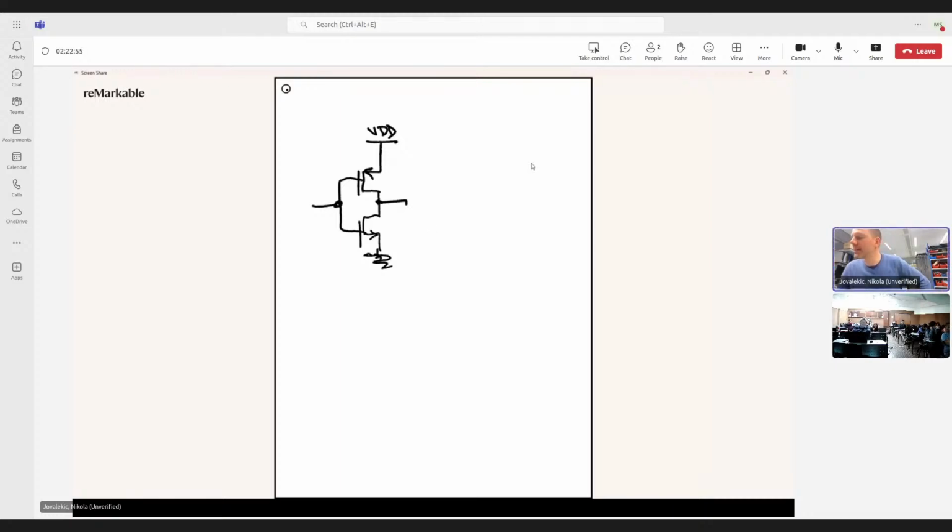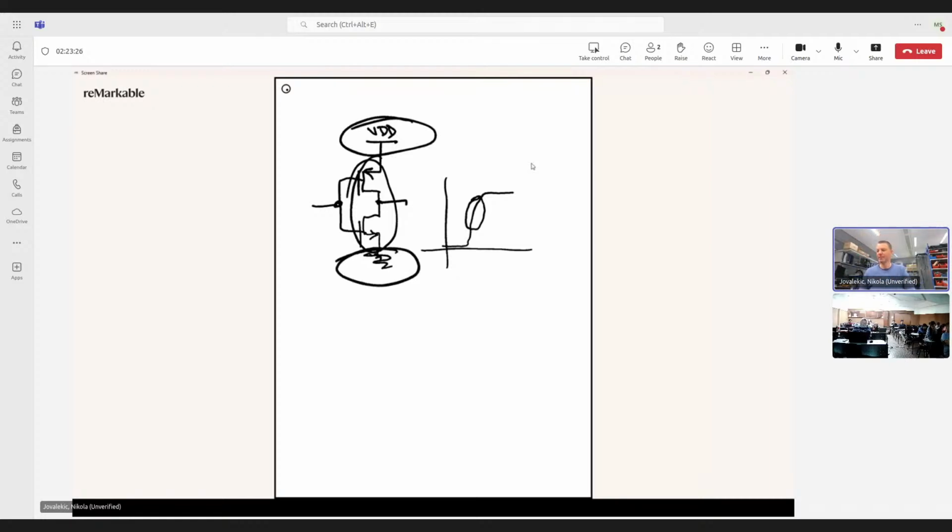So this is a CMOS inverter, it's used to build any logic in modern CMOS design. When you go from, I don't know, logic 1 to logic 0 to logic 1, you will have some period where both of these transistors conduct. What practically happens here is that you will almost short circuit the power supply in your PCB with the ground. Now imagine what happens when you have millions of these structures and they start switching from 0 to 1 at a very high frequency.